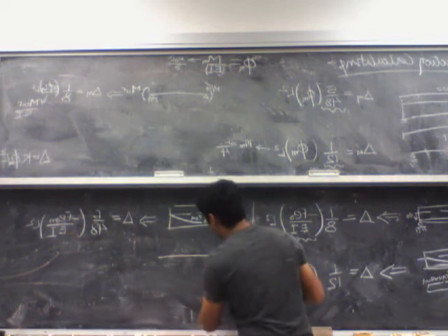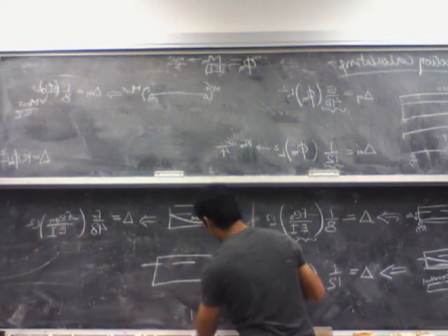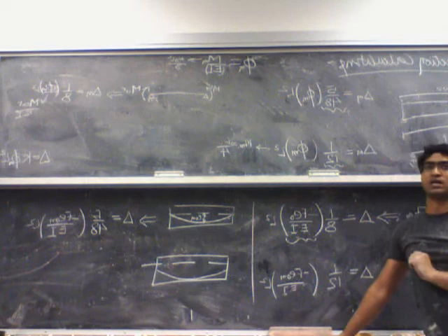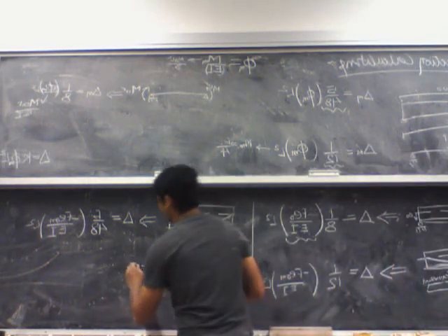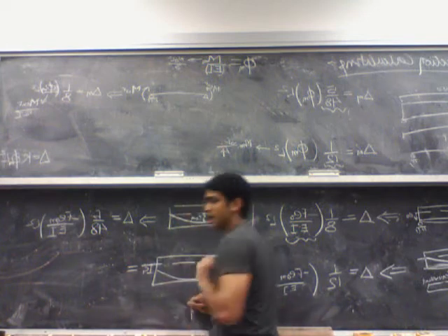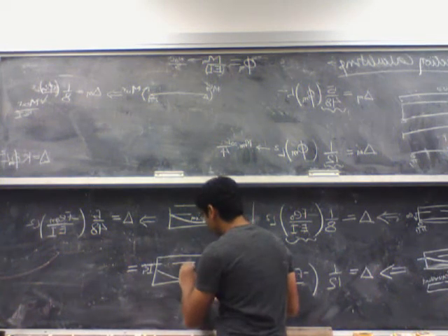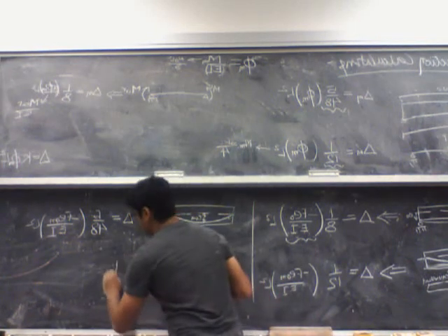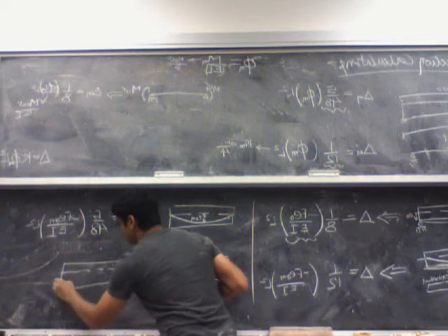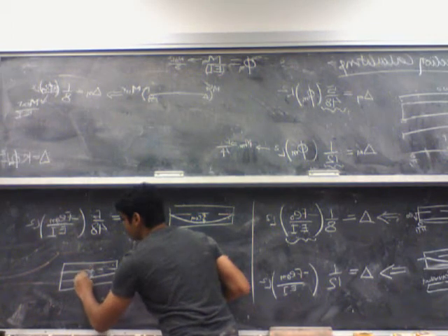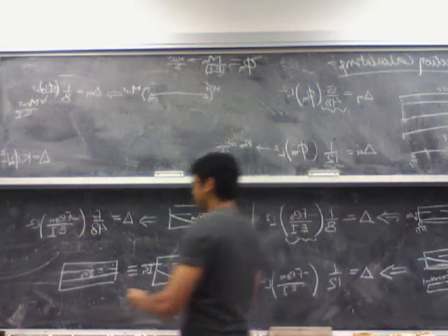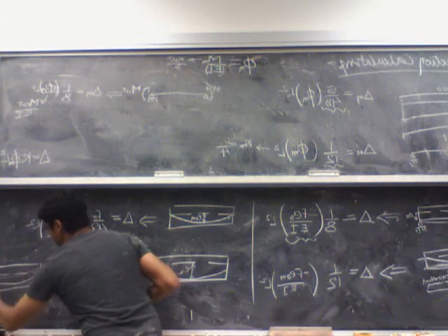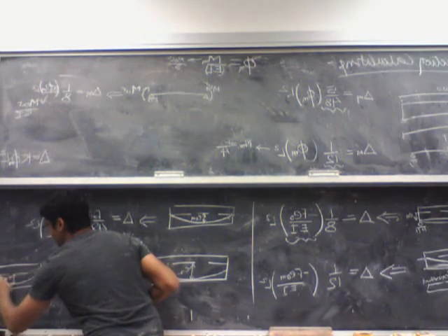So the question is, what if I have a strand which is parabolic but doesn't go back to 0? What do I do in this case? So in this case I can do, let's say this one is e1 at the ends and this is e2 at the midspan. So what I can do is I can break it into two parts. The first part is a constant e1 throughout, right? Plus a parabolic case where it goes back to 0, where at the midspan it's actually e2 minus e1.